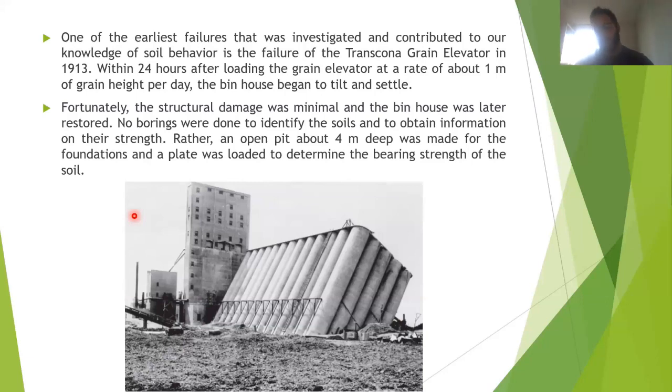Like you will get that feeling with your experience. So you can imagine that the foundation is going to be at 1 meter, and someone already decided that you're going to have a mud foundation, and then you took samples right beneath the foundations, and you took some samples deeper, because the stress influence of the foundation is 3 times the width of the foundation, or if it's piles, then it's 10 times.